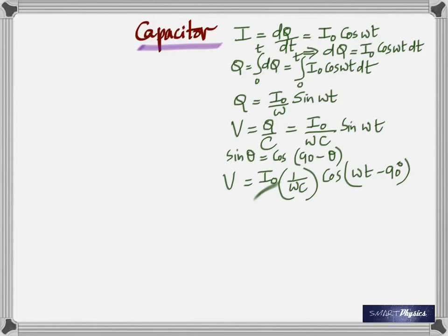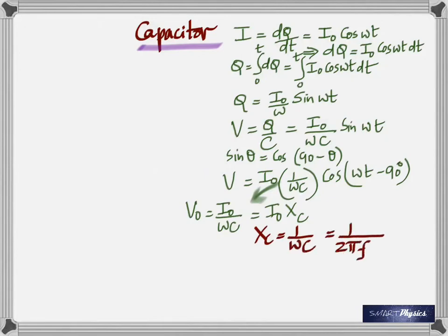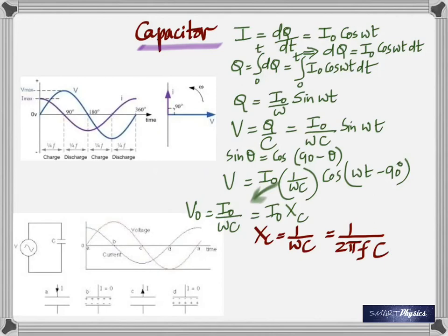Because according to Ohm's law, you got to have this in place of resistance. Voltage is current multiplied by resistance, isn't it? So this whole thing is what? Capacitive reactance. Okay. So when you take a look at that, you understand that that's a completely different behavior. Because now you know that XC is 1 by omega C, and therefore as the frequency increases, what happens to XC? Decreases. And therefore, if the frequency is 0, what's XC?